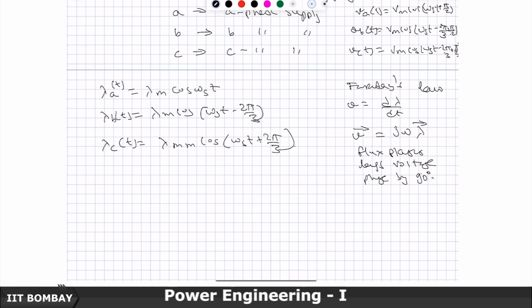This is basically the idea, that when the 3-phase distributed winding in space is connected with a proper phase sequence of ABC to a 3-phase power supply, which is 3-phase in time, then you will get a rotating MMF wave, which you can basically visualize as a north-south magnet which is rotating at the synchronous speed. So you can visualize it like that.